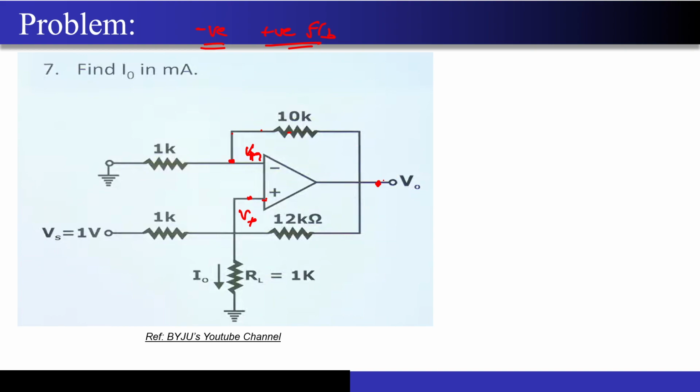So now if I'm already applying some input over there, I need to short all the voltage sources that are present in the circuit. So I will be just shorting this for that particular purpose. Now if I give an input at V0, right? See, I just wanted to check for the strength of the negative and positive feedback. But since the op-amp is ideal, again the current that will be flowing into the negative and the positive terminals is going to be zero.